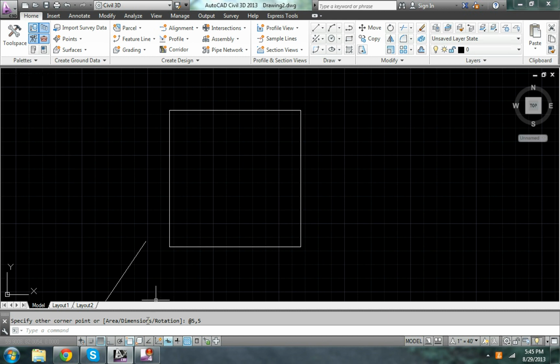This is the start of our fountain. I'm going to go to Object Snap down here, and that allows me, if I create another line, so I'm going to hit L, to snap to certain things. So this is an endpoint snap. This is a midpoint snap. So I'm just going to draw a bisector in my rectangle, square. Hit Enter now to get out of that. Exit also gets out of things, so if you hit exit, it will say cancel on the command bar. That's cool too. And now I want to create another one, but I want it to be rotated 45 degrees. So I can use this rotate command up here, or I can type it.